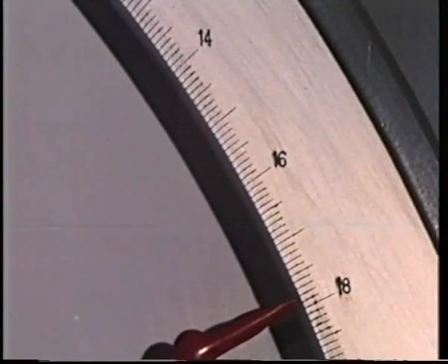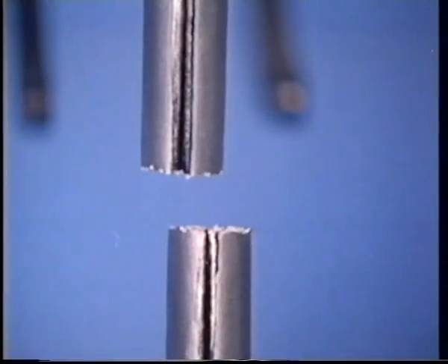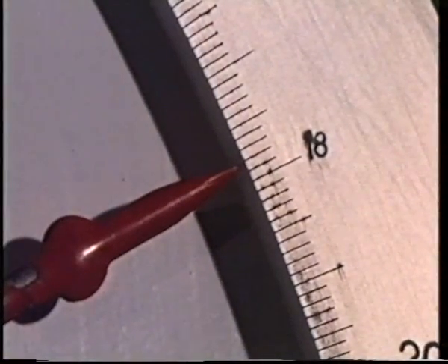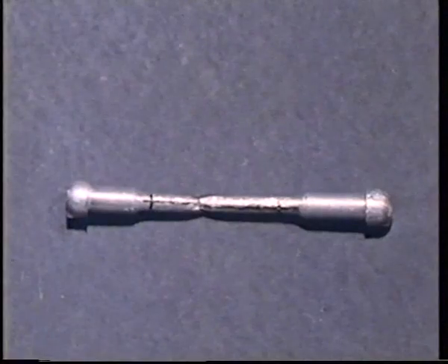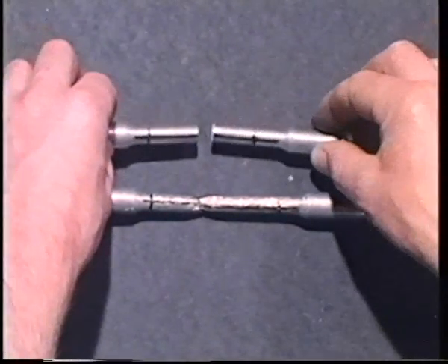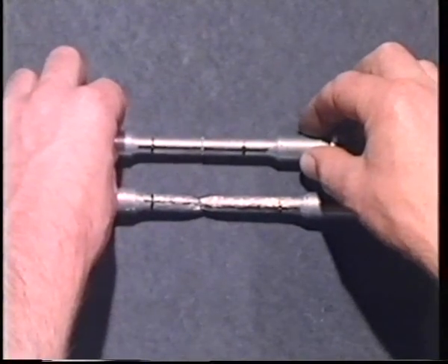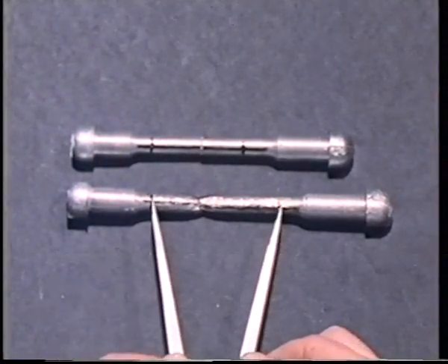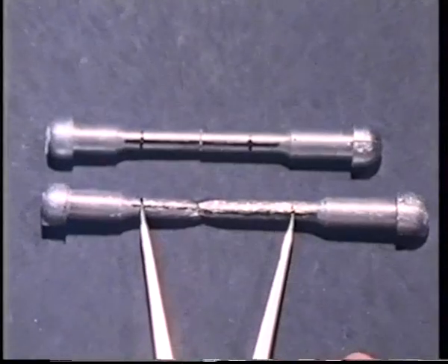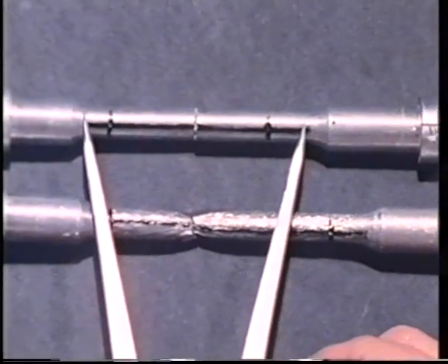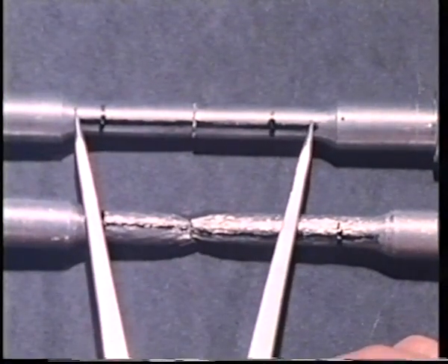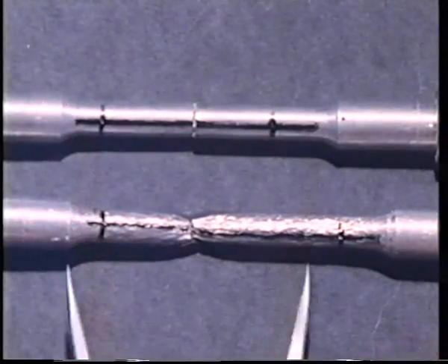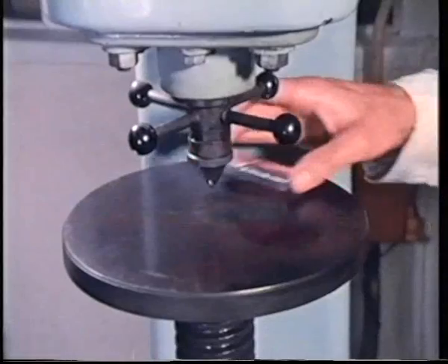By forming an alloy, we've brought about a useful change in the mechanical properties of the aluminium. We've increased the tensile strength. But strength isn't the only property that's changed. When we put the broken bits back together, we'll find another. By comparing lengths, we see the pure aluminium stretched more than the aluminium alloy. This means the alloy is less ductile, so there's been a decrease in ductility.